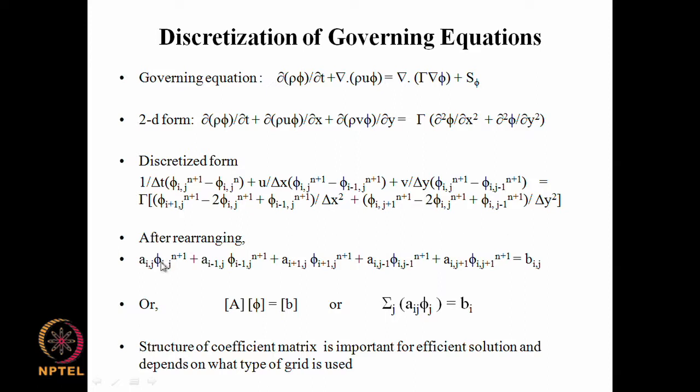This is our algebraic equation, and in the process we have linearized the u and we have accounted for the involvement of other equations, the coupling with other equations in terms of v here. And for example, in the x momentum equation we have a source term which is not mentioned here, which is the pressure gradient term. So all those things are done and eventually we have an equation like this,